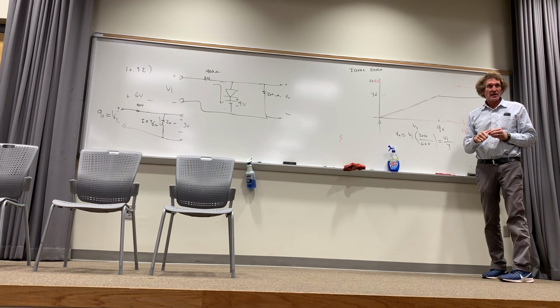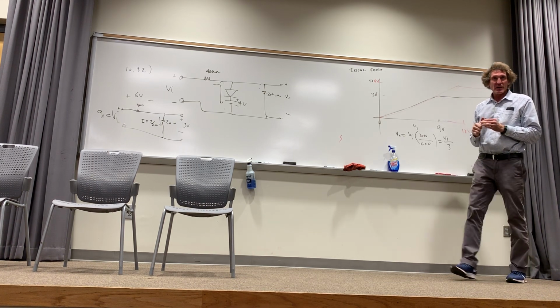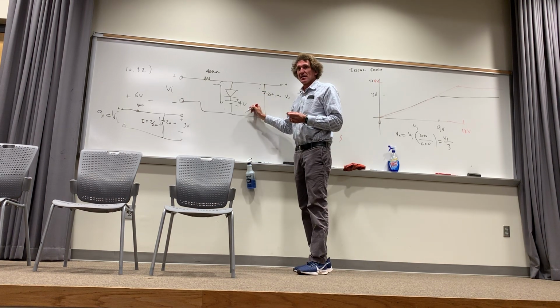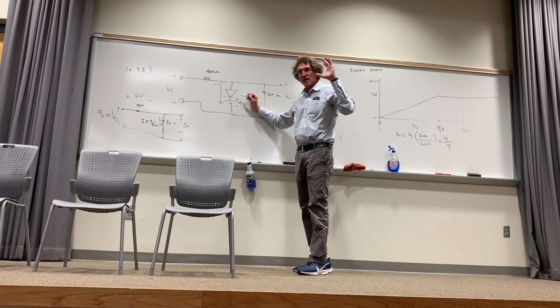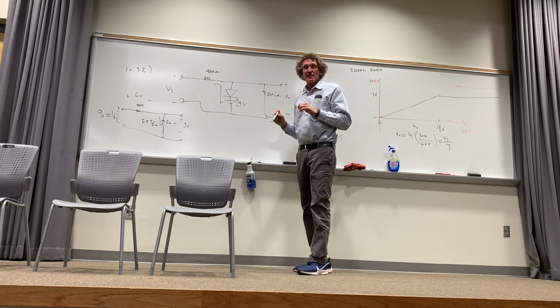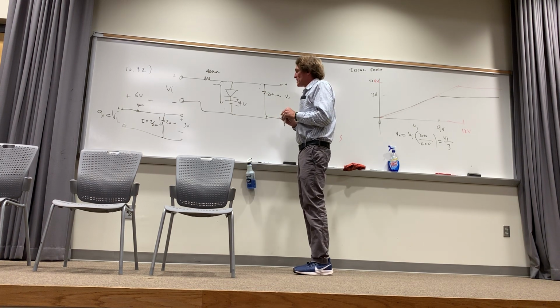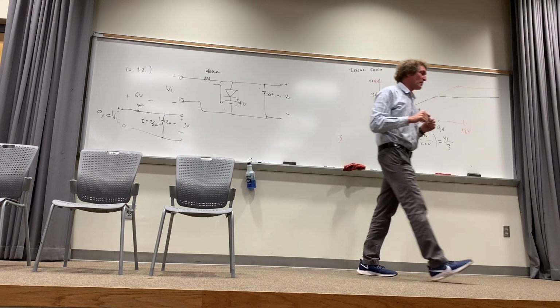Everybody see that? Give me a show of hands if you do. It'll bother some of you. You'll start wondering about this. This is limiting the output voltage. There's an actual diode that does this. It's called a Zener diode that we'll get to. A Zener diode, until you hit some threshold, will not allow current to flow, and it's a threshold voltage. So this is limiting the output voltage, and there are a lot of applications for this that we'll get to. But this is for an ideal diode. I'm going to cover one or two more.